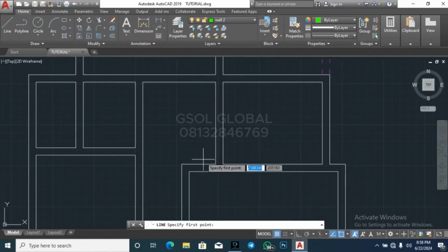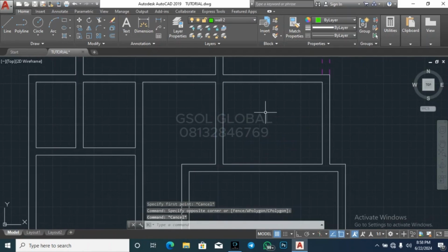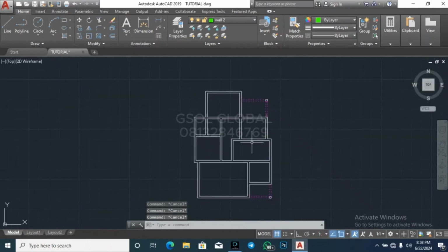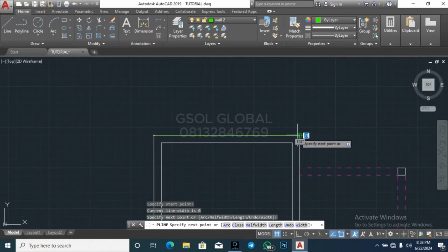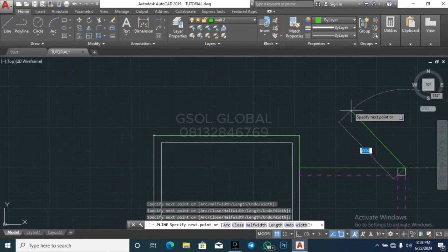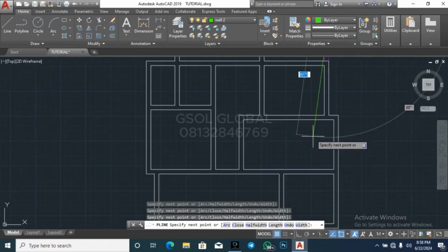So if you are placing a wall, it's either you place it on top of this wall for your first floor, or you place it at least 600 away from this wall. So that's from any wall here. If you're placing any wall here, it should be 600 away from that wall. All right, that's the rule. So we are going to go with that and apply the rules. So now I'm going to draw the exterior wall as usual.